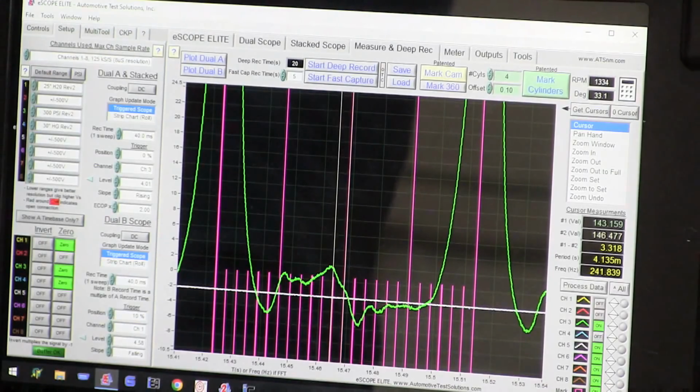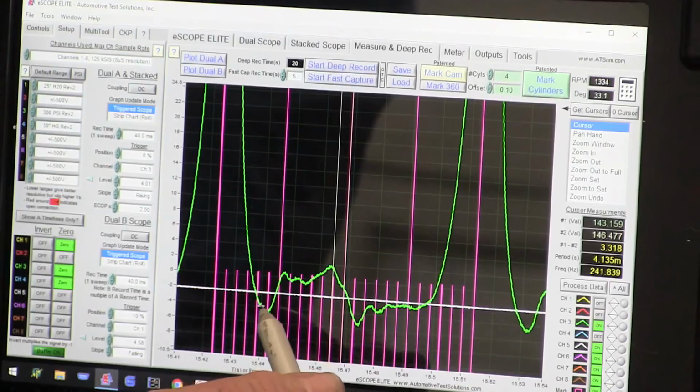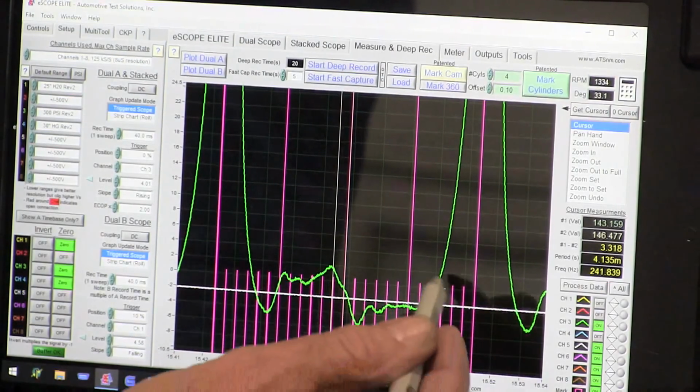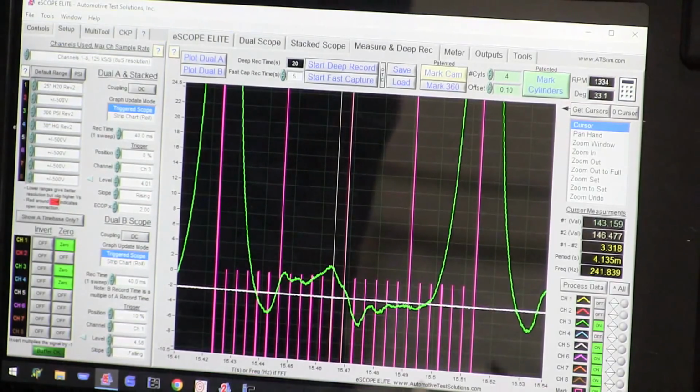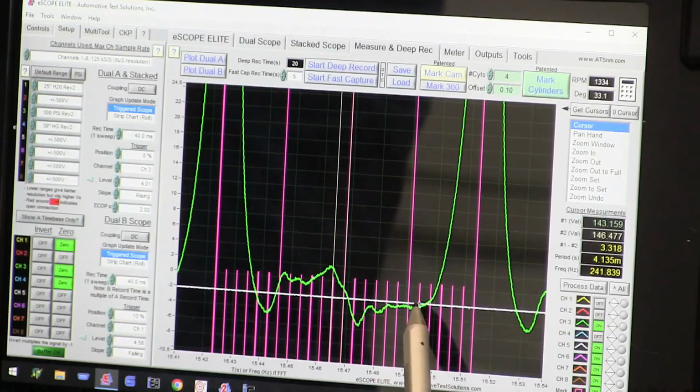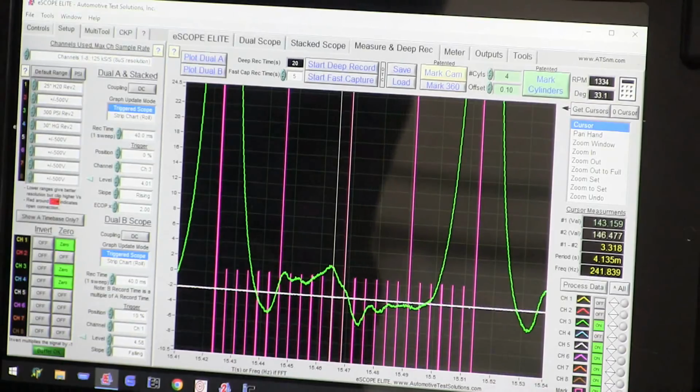So that's a couple of teeth, or the phaser is on. So we need to check the phaser. Again, the exhaust seems to be pretty close to being on target, but the intake appears to be off to me. This is not what I expect from these 3.6 engines. I expect these are usually late. The intake valve opens late, and the intake valve usually closes late. Like it closes at about 75, 78 degrees, 70 to 78 degrees closing, and about 10 to 15 degrees after top dead center. So both of these are happening before they move to the right, so the cam is advanced.